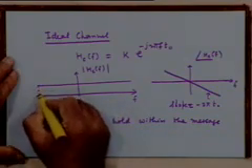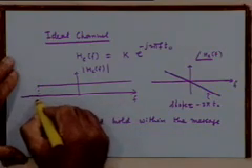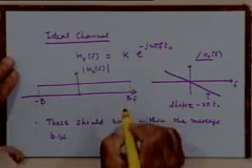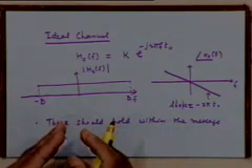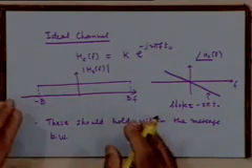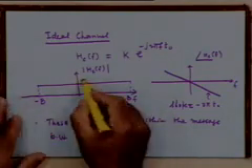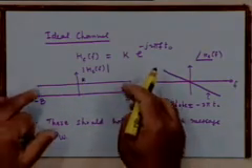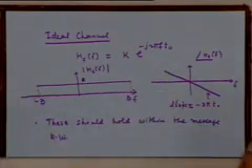So let us say the message bandwidth is b. We would like the transfer function magnitude to be constant, equal to k, between minus b and plus b. Whether it is constant beyond that is not of any interest to us, right? It may or may not be, because the signal does not have any frequency components there, so it won't bother us.